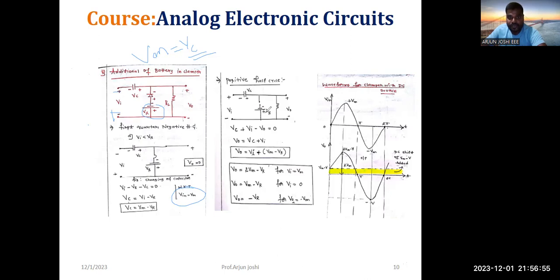And in the positive off cycle, our diode will act as an open switch. Please apply the KVL, minus plus to minus minus. Apply like this, plus to minus, minus to plus plus Vi, minus to plus plus Vc. I just interchanged here. Please make it correct. Vi plus Vc minus V naught is equal to 0. V naught is equal to, you take this one to LHS, and this remains in the RHS, Vc plus Vi. You can substitute here. Vc is equal to Vm minus Vr, and remaining same Vi. Okay, just substitute Vi is equal to Vm. So 2 Vm minus Vr.